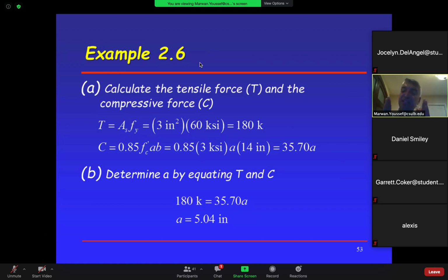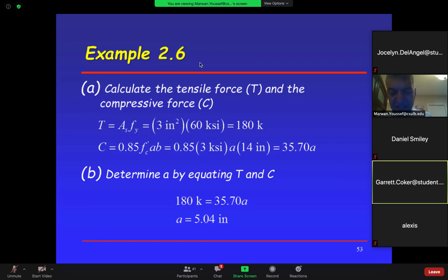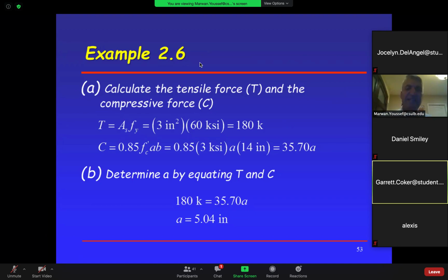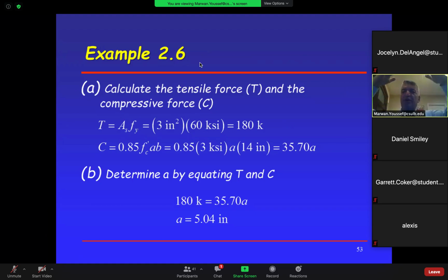But when the beam is not cracked, it's half of H, H over 2. Remember, we did that before. So the only time we can use the geometry of it is when it's uncracked? Absolutely, yes. That is true. If it's uncracked, then it's H over 2. If it's cracked, then you have to go through this process to find C. Because the neutral axis is going to keep going up, because remember we're losing the concrete, so it's going to follow the solid concrete.